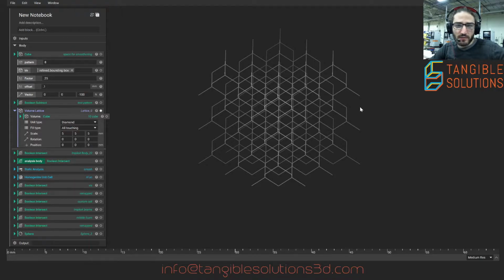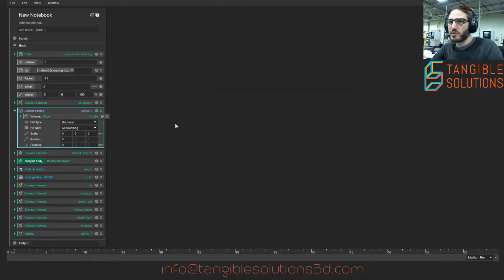On the opposite side, we have sheet-based structures, TPMS structures, those things which exhibit a very high surface area for the volume that they represent. They have a couple of really cool, novel mechanical properties. I wanted to have a hybrid between the two, but still have a custom unit cell. There is an array tool inside of nTopology.